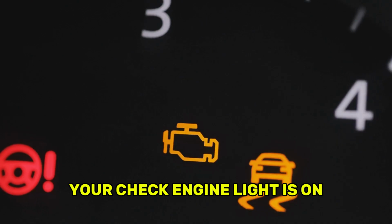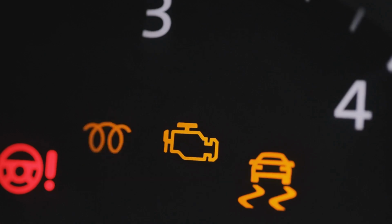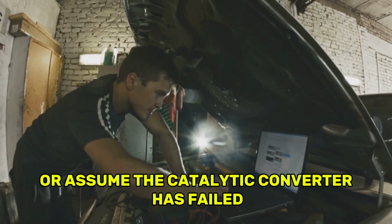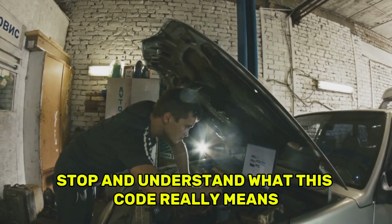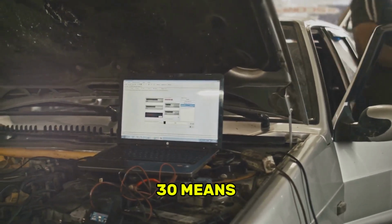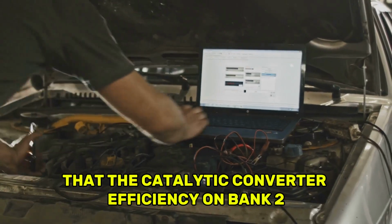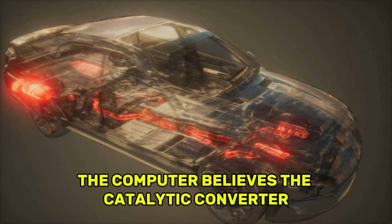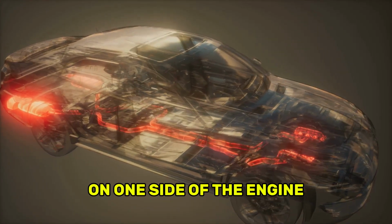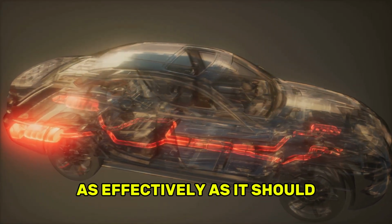Your check engine light is on, you scan the car, and the code P0430 shows up. Before you replace parts or assume the catalytic converter has failed, stop and understand what this code really means. P0430 means the engine computer has detected that the catalytic converter efficiency on bank 2 is below the expected threshold. In simple terms, the computer believes the catalytic converter on one side of the engine is not cleaning exhaust gases as effectively as it should.